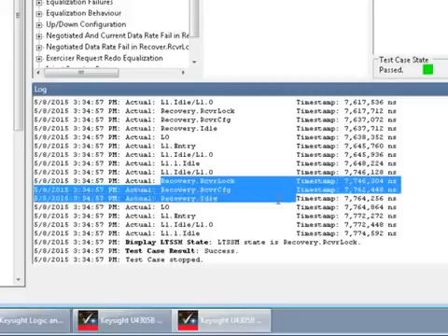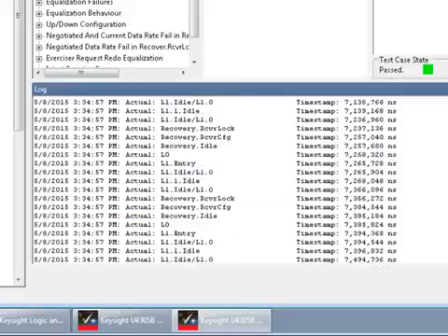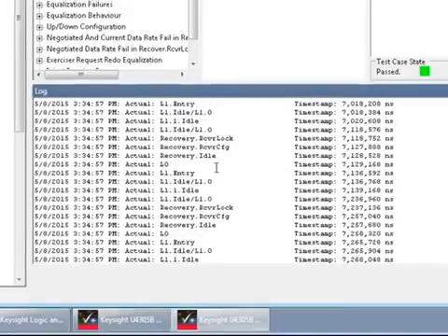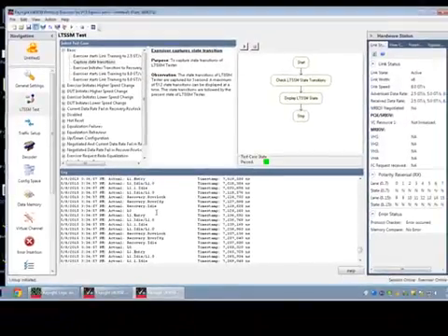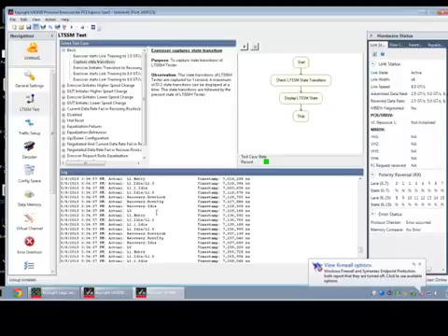Then it went through recovery. The clocks actually came back, the signal was there, it locked onto the signal, and back into L0. And you can scroll through this list and see the timestamps as that link is going in and out of L1 substate over and over again. Great validation. What if I want to do a little more testing of true algorithm type analysis of that?